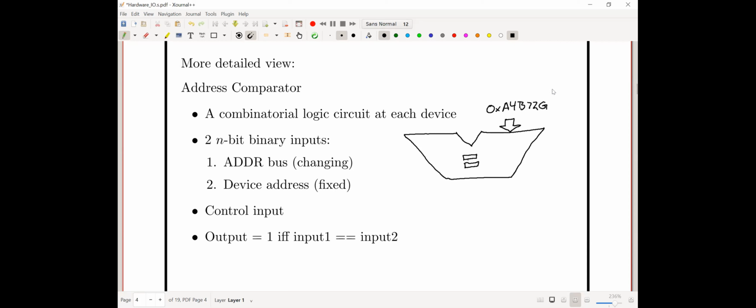Let's say that's a memory device, but not an individual word of memory, but a chip. And then we have the address bus connecting over here. Often we draw a line like this with a number like 16. That diagonal slash indicates that there are 16 wires.